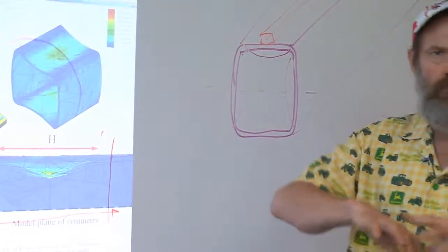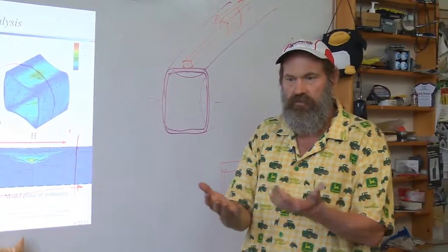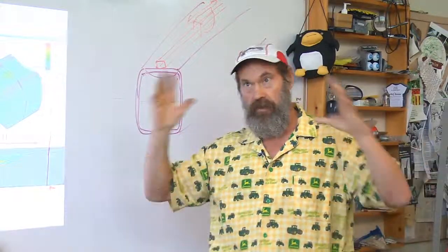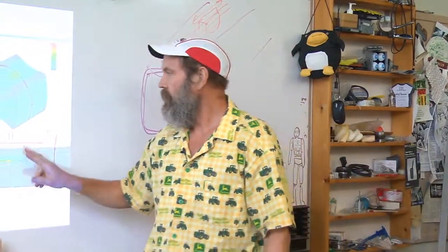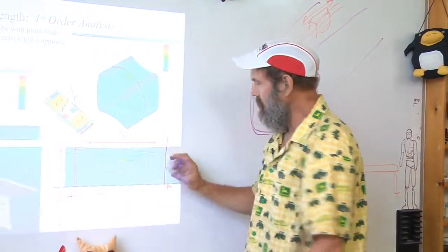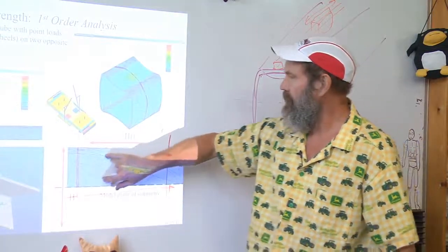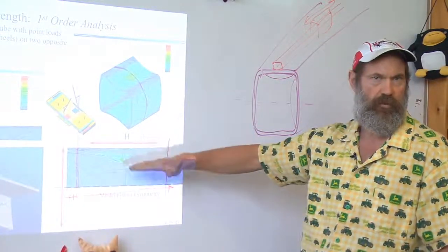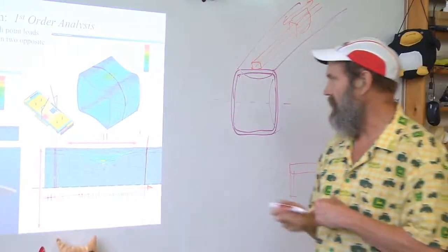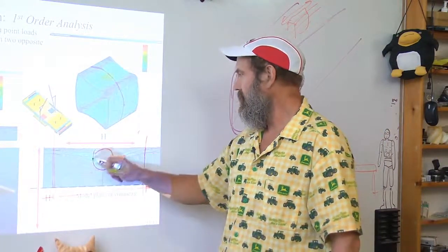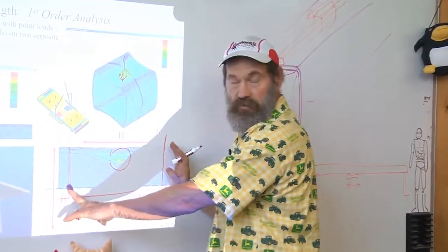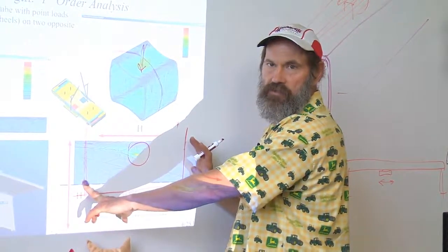So when you have a large structure and you're looking at doing the analysis of it, you can sometimes say, oh, how do I do the analysis? It's got a point load, long beam, oh. You can start to guesstimate what's going to happen just by thinking in terms of St. Venant's principle, that the material far away from here really is not doing anything to support this. Indeed, if I wanted to estimate what is this point deflection, I wouldn't even take 3 characteristic dimensions away, that is too much.